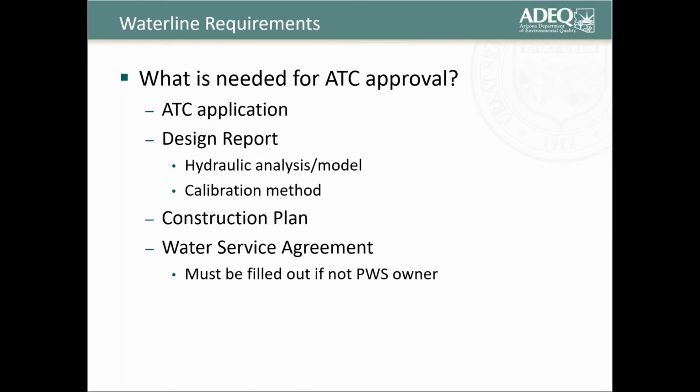And then moving on to the construction plan, we look at the water line and its aspects, looking at the valves and the depth from the ground to where it's buried, and checking up on all the requirements for the water line. And then the water service agreement must be filled out, but if the public water system is the applicant, then it is not needed.